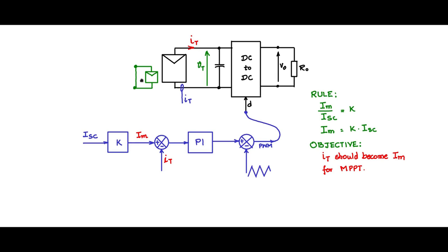You short the terminals and use the short circuited reference cell for obtaining the ISC. You sense the current through a Hall sensor or a similar method and connect it to ISC, and this ISC is supposed to represent the short circuit current of the main PV array if these two cells are from the same manufacturer and have similar datasheet specs.